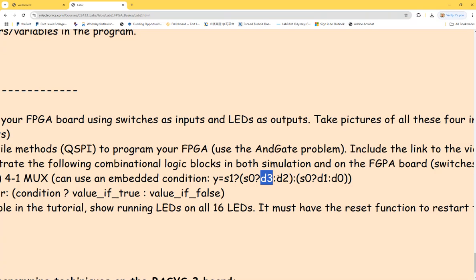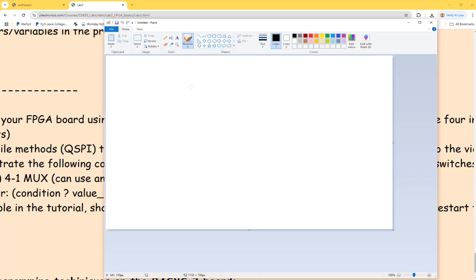So in that case, if I'm having 1 1, which signal line is being picked up for the mux? So what is the mux? Just a really quick review on it. If I've got a 4 to 1 mux, which means I have 4 signal lines, it's going to pick up one of them as the output. So if I have four options, I need 2 bits for the selection. That's why you are seeing S1, S0, right?